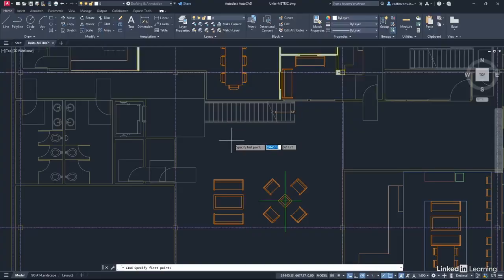Below. Click about there, and you'll see now that we're going from that random point we selected. But now the dynamic input is prompting us for an angle and a distance. So if you bring your crosshair so that it's horizontal, like that, can you see our green polar tracking line kicks in. Now, as we drag along there to the right, can you see along that tracking line, we get a value highlighted in blue. Now, that's in metric millimeters in this case. So I'm going to type in 2500 like so, and just press enter. And there's our line, 2,500 millimeters long.